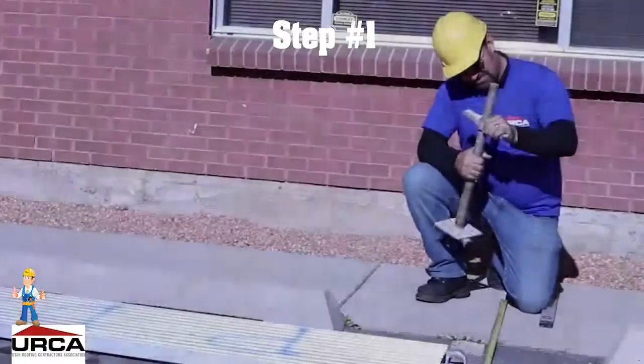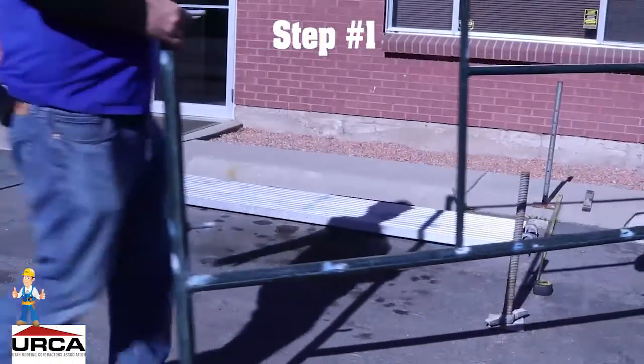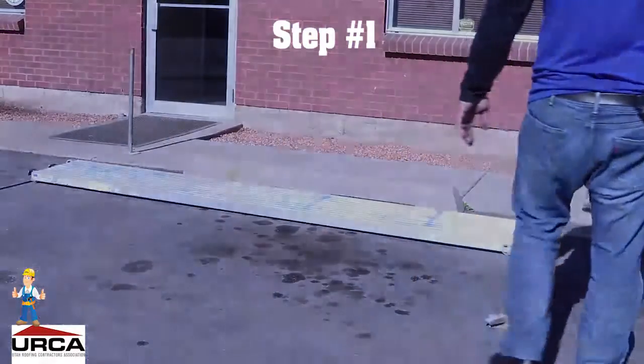There are 10 steps to erecting a scaffold. Step number 1. Use footings that are level, sound, rigid, and capable of supporting the load without settlement or displacement.